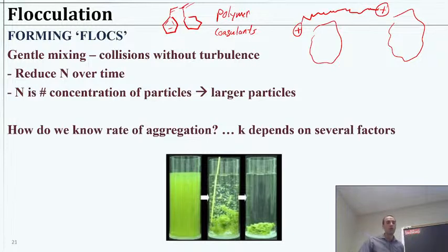Okay, so flocculation then. We want to create an environment for the particles to stick together. We do the actual encouragement of them to stick together in what we call the flocculation process. So this will be gentle mixing, enough to let particles meet each other, but hopefully not so turbulent that they will also be ripped back apart. Because you can imagine stirring very fast will cause some shear forces. Particles that maybe did stick together would be pulled apart, right, if you stir too fast.